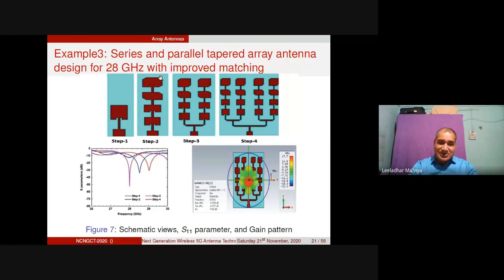So this is two upper side patches chopped from the opposite corners, and the reason is that this antenna was unable to move completely in the linear polarization or in circular polarization. That was moving in elliptical polarization. So one confirmed polarization must be done, either the circular polarization or the linear polarization. So by doing this chopping from the opposite corners, we have converted this into completely linear polarization, right?